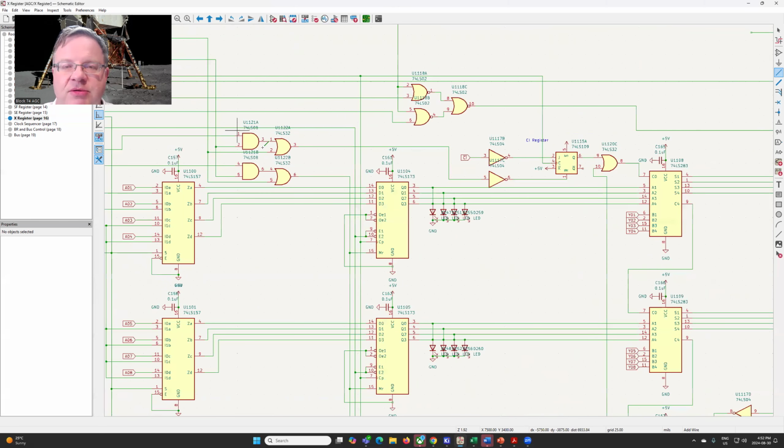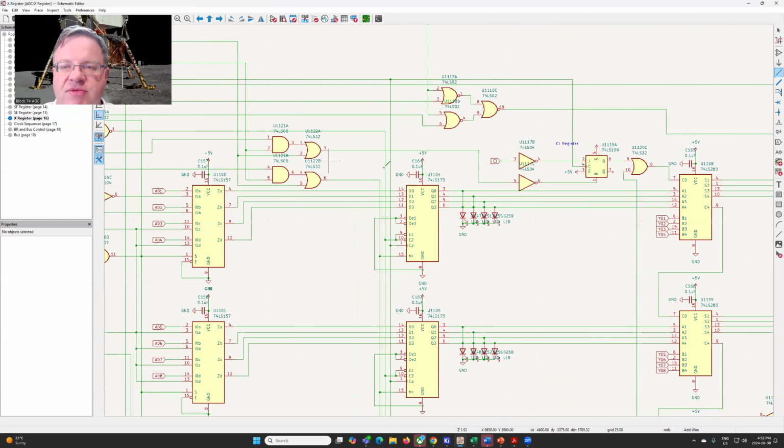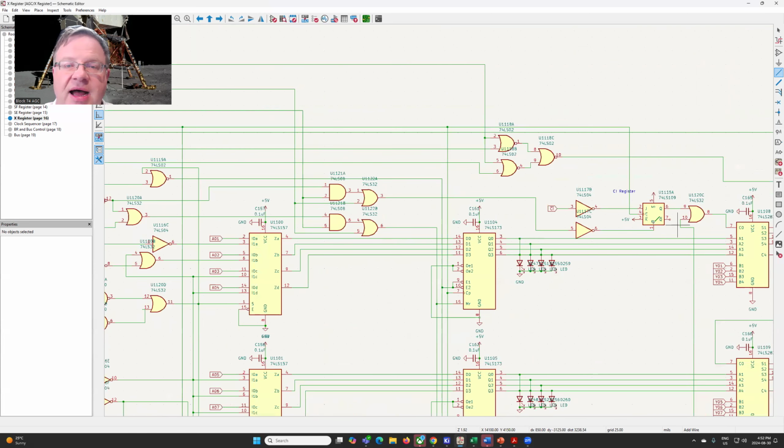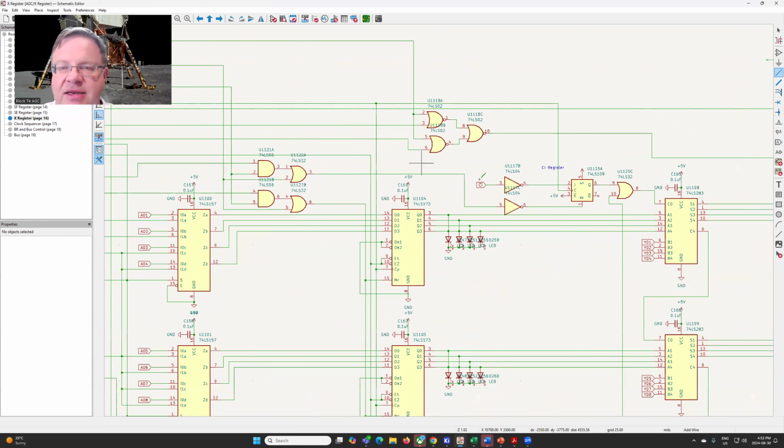Some of the logic that we talked about in the last session is that there are certain scenarios where we have to clear our CI register. So some of the write pulses that go to the Y register, WY, WYD, and WY12, not only write data into the Y register, they also reset the CI register, or the CI flag, or carry in flag, so it can potentially be set based on other operations as part of the sub instructions that are being executed for various instructions.